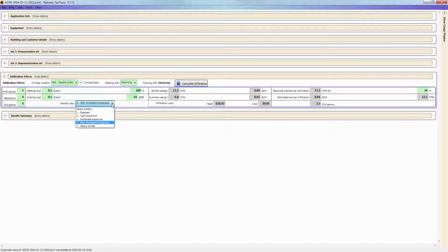The shielding, which affects the air change rates. And you'll see here that we have a winter design natural air change rate of 0.04 air changes, 0.02 air changes, and this is for a house that has a little bit over the passive house standard, and we worked out about 12.5 CFM total average natural infiltration rate over the entire year, 24 hours a day over the year. And using the old 20 factor we came up with 10, so that was a bit on the high side.